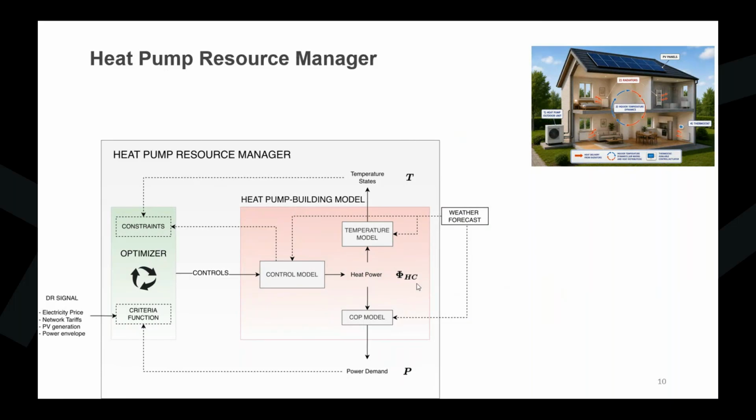So the optimizer essentially uses the model as a simulator in order to optimize the operation of the heat pump. At each operation, it proposes certain control inputs, which are then evaluated by the model and fed back to the optimizer, which then calculates the constraints and the criteria function.